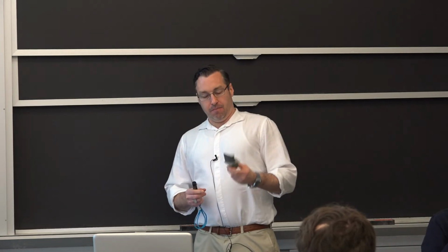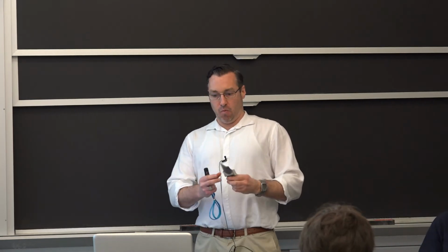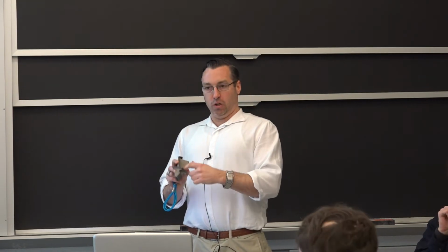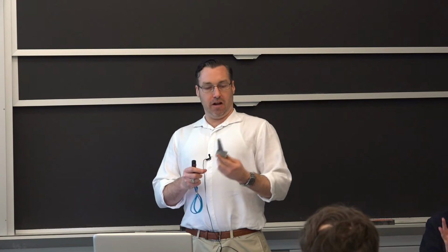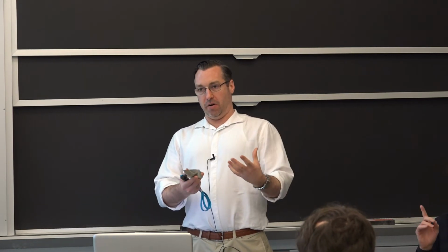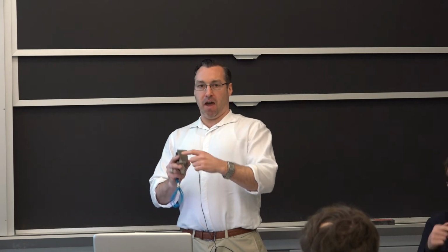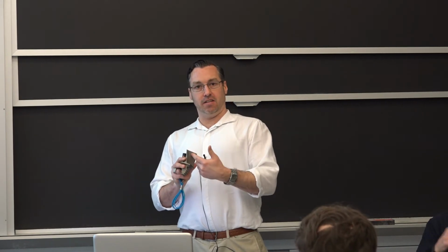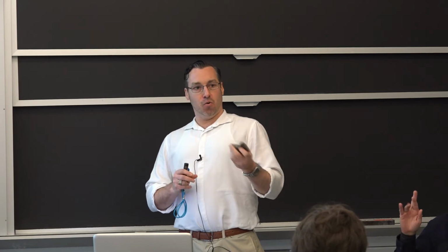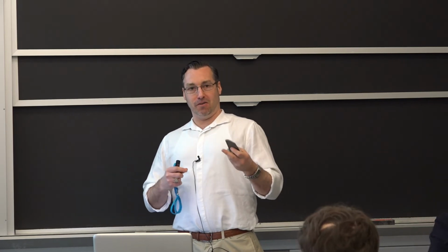So this is a turbine blade here. What you'll see is they actually laser drill in cooling holes. And Professor Eager, I think in one of the previous lectures, showed one where you can open it up, and you have various cooling passages that run inside this blade. So air actually comes in and passes through to cool it while it's operating so it doesn't melt in service.